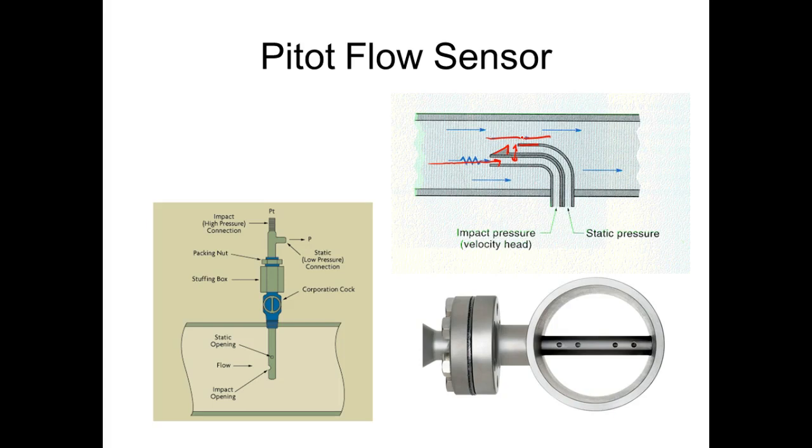I know what the angle of attack is, right? Everybody understand that? So when a plane's coming in for a landing, you ever see them, they're not flying level, they're nose up like this, right? You understand? And what happens is they adjust what they call the angle of attack. An angle of attack is the relationship of the plane to the direction the plane is flying. So they always do a nose up. If they get the angle of attack too high, then the plane will stall, and then they'll crash.